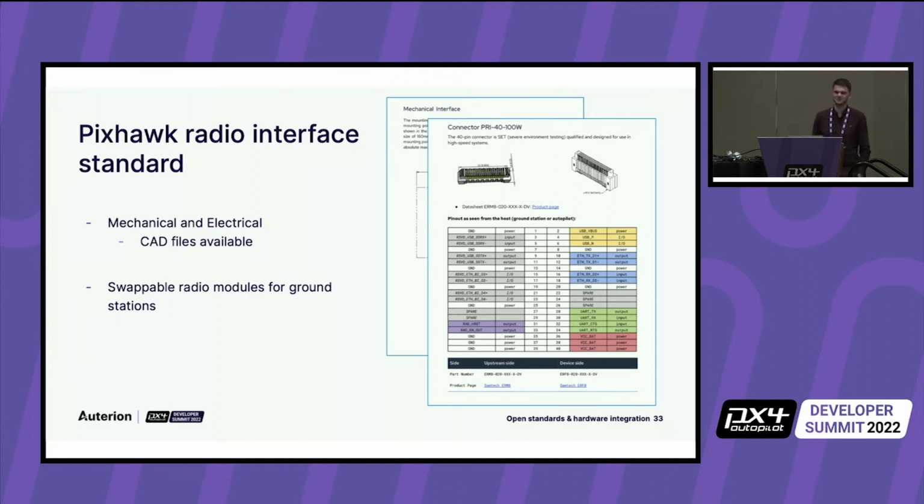Yeah, I mean, S-Bus is just one pin, really. Proprietary protocol, right? It's basically UART, but with inverted polarities. So it is standard as far as I know. But why did you have to change? I think it's in PX4, right? There's an S-Bus driver in there. But didn't it work? Oh, it works, but is it a standard? That's what I'm asking. Is that part of the standard? Because I didn't see it in the doc.